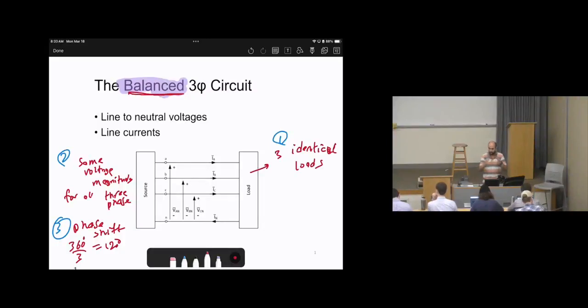In other words, you are connecting at phase A with angle 0, 120 volts, angle 0. Your neighbor will be with 120 volts, angle negative 120. The other neighbor, 120 volts, angle positive 120. So when you have different angles, this will not impact the load. The load will run with any angle, there is no problem. But here, we choose these angles as 0, 120, negative 120 on purpose. Why? What's the point of using this phase shift? Why wouldn't we use them all as zeros and stop?